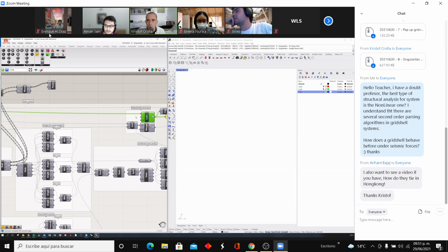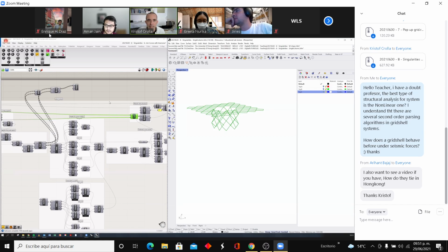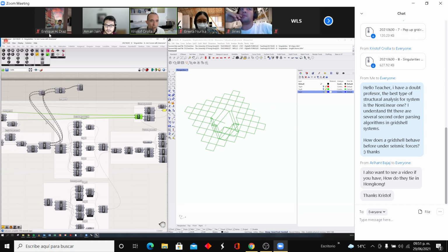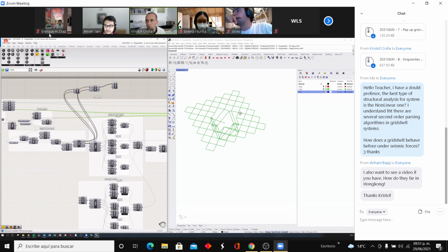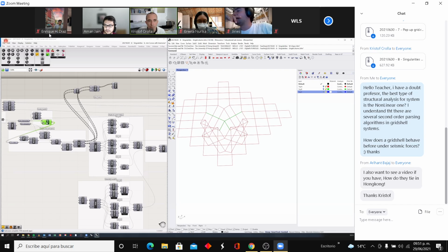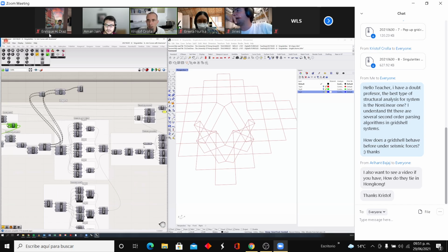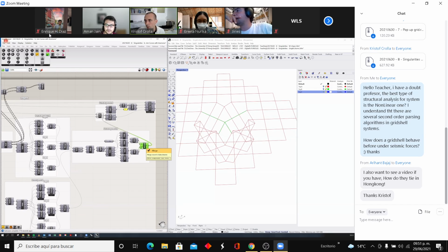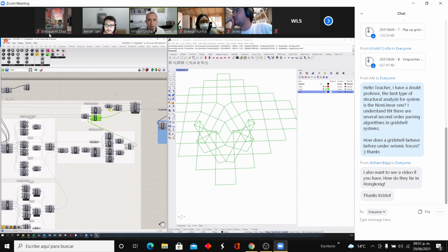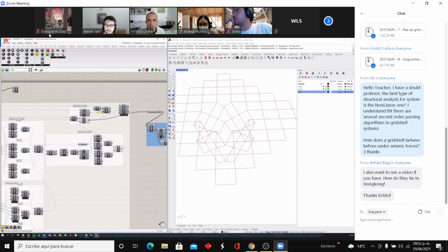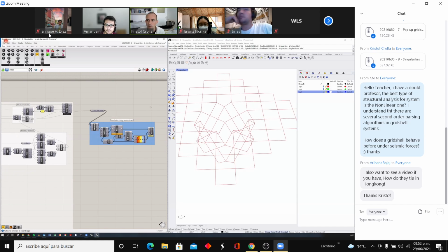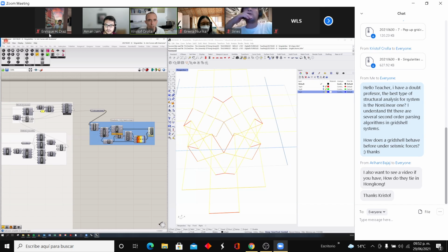And then the curves that I had, I'm deleting the ones that were selected originally. So these 4 curves here that I had in the beginning, I remove from the list, and I'm replacing them with my newly joined curves. So it looks the same, but now this one is connected to that one. And I'm merging these two lists. Let me quickly visualize that. You'll see the yellow lines are actually connected, but all the other ones are not.